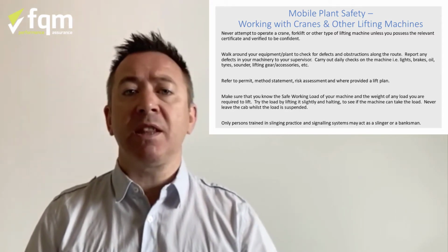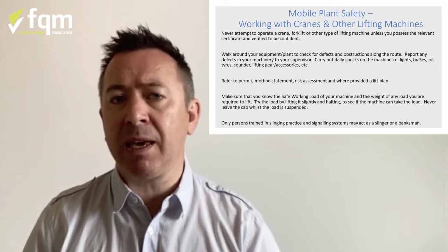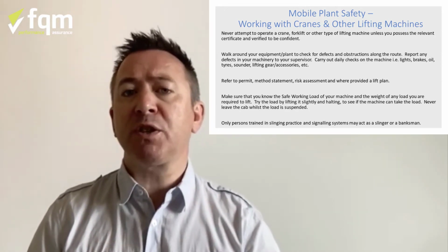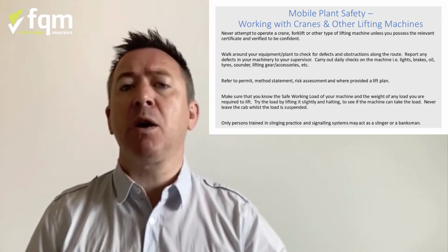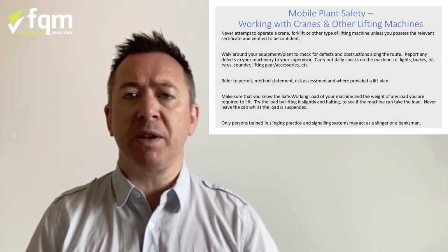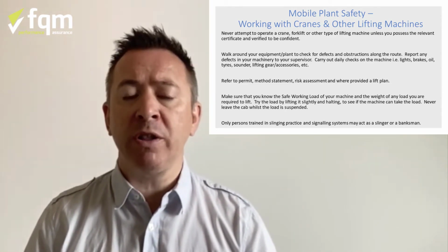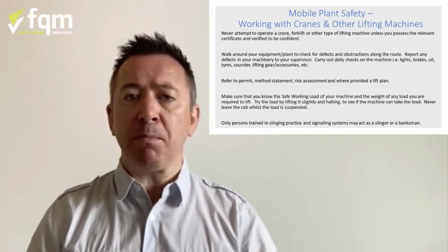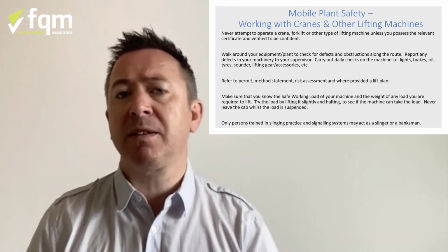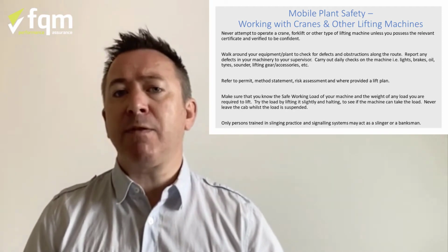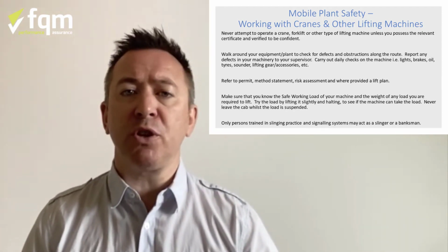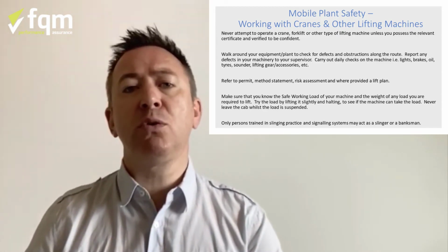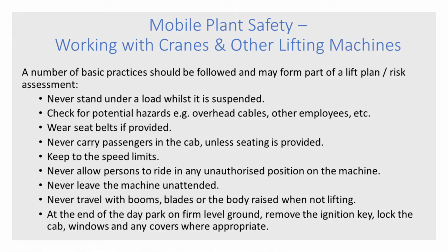It's also important that we think about the route that we will be taking for this crane or this forklift. Is the route clear? Is it correctly barriered off where appropriate? Are other operations that are going on being made aware of the activity that you're going to be carrying out? And it may be that permits are required in order for that to happen. You must also understand the safe working loads of the equipment that you're going to use and the load weight of what it is you're going to be lifting. There are rules around this, and often companies put in place lifting plans associated to this.